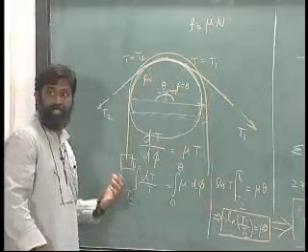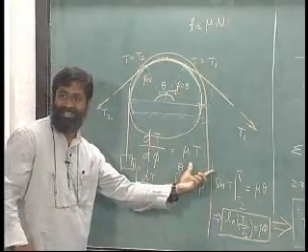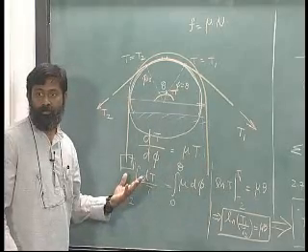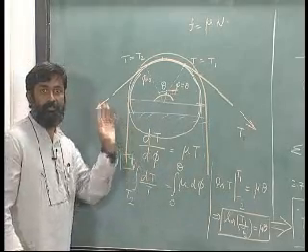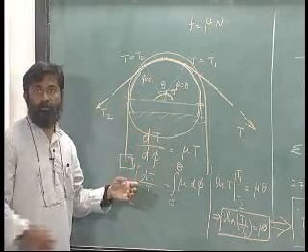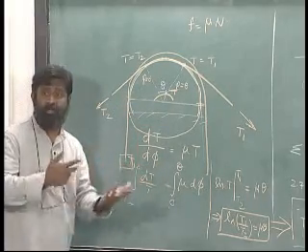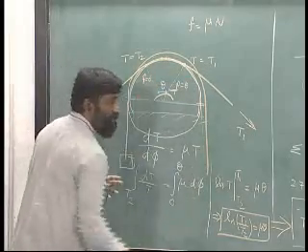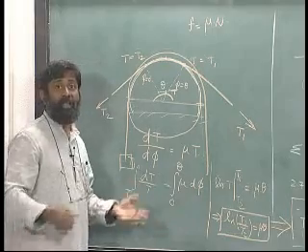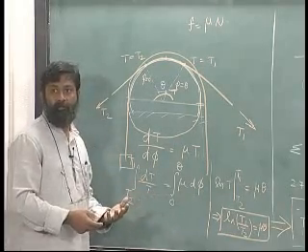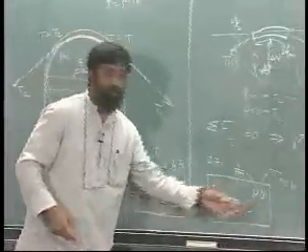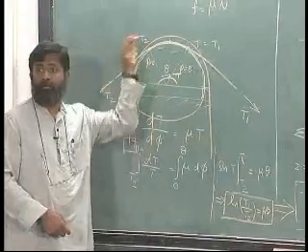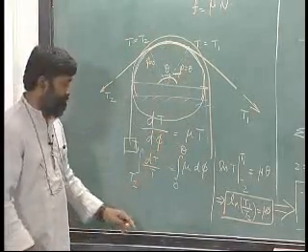In order to pull this, I have to apply 20 times this, and this is an important application in mechanical engineering. This is what is used quite often in order to make sure that there is no slipping occurring. So, when I have a pulley like this, I will just make one more rotation like this and take it. I am guaranteed for most part of it, unless mu tends to a very small value, it is possible for me to keep in contact with the pulley. Okay. Thank you.